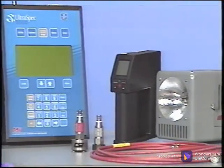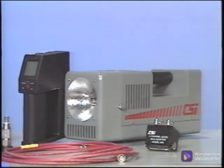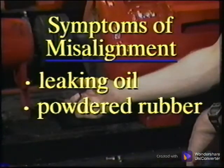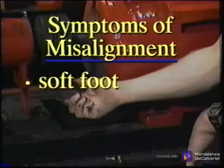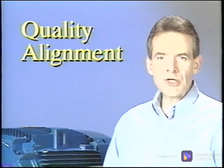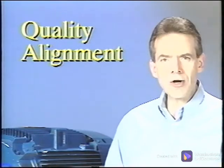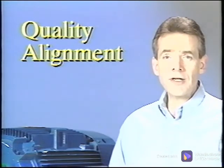All of these methods can be used to detect misalignment, but other symptoms of misalignment are apparent without the aid of tools or instruments. Some of these symptoms are excessive oil leakage, powdered rubber under couplings that use rubber inserts, leaking seals on pumps, soft foot condition, broken foot bolts, oil shimmering under the machine foot or base plate, and premature failure of bearings, seals, shafts, and couplings. The benefits of precision alignment far outweigh the costs, and the price of poor alignment is much higher in the long run than it first seems. There are many methods for proper shaft alignment, and they're illustrated in the next section.